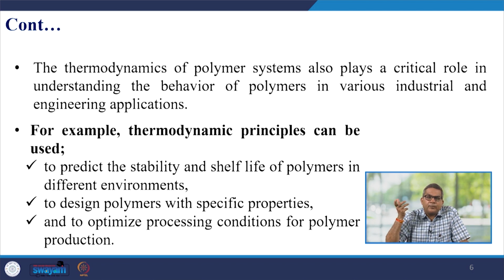Let us take an example. The thermodynamic principle can be used to predict the stability and the shelf life of a polymer in different environments. Like if you are using any chair from 0 degrees Celsius to say 47 degrees Celsius atmospheric temperature, then how can you predict the shelf life of a polymer, up to how long it will remain in a workable situation. The thermodynamic data is useful in predicting such kind of life cycle analysis.